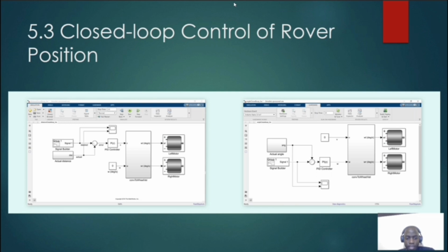PI controller provides an output based on the current error and gives a quick response. The integral part accumulates the error over time, which is essential for eliminating any small steady-state errors, ensuring that the robot reaches its target precisely.